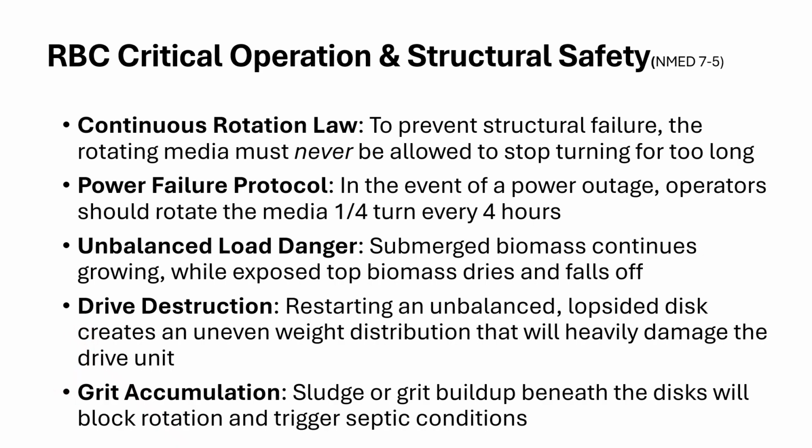Another thing to look out for is grit accumulation. If we have a sludge or grit buildup beneath the discs, we're going to stop the rotation, and we're going to allow for septic conditions. We're not going to have the aeration we need. That grit and that sludge can block that. We're going to have septic conditions, an odor problem, and we're not going to have an efficient removal of BOD. Okay. A couple of really good test questions for troubleshooting for level 3 and 4 on this slide.